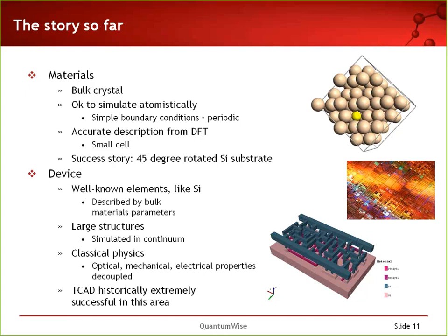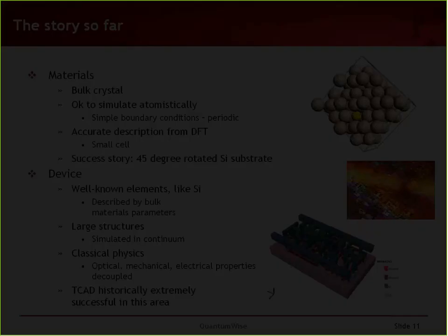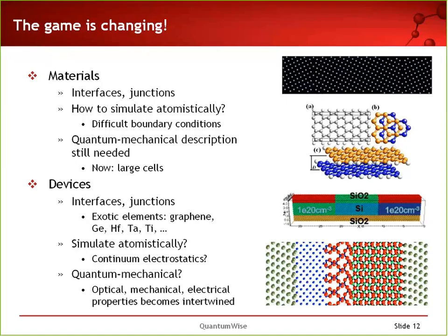So you don't really care about the atomistic structure of the device. Everything is described by bulk materials, so you know what the conductivity of silicon is, you know how that might depend on strain, and so on and so forth. Now, this picture really changes, because the device is becoming so small that we really have to look at the individual atoms, as I mentioned before. We have to start introducing quantum effects, and this fundamentally changes the way we simulate the device.